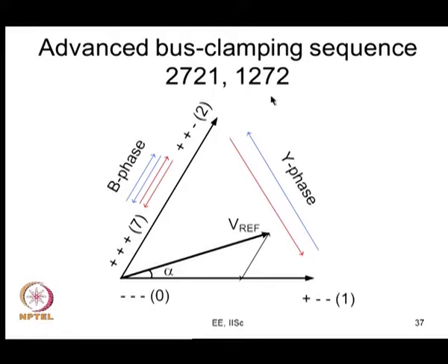So, you have these special sequences which switch twice. You can see that in a half carrier cycle a phase can switch only once in triangle comparison based PWM, because it can only intersect once, whereas here you can see it is switching twice. So, this is a benefit that we are getting. We are able to divide an active vector time. This active vector is applied twice, which is not possible normally in methods like sine triangle PWM, etc. There, an active state will be applied only once.